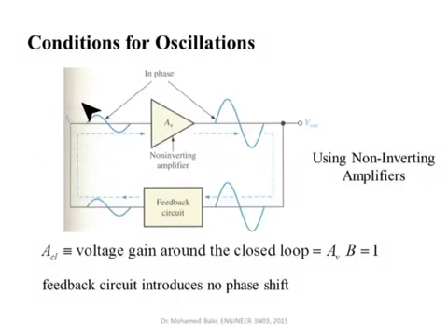So if this was 1 volt in amplitude, this is 10 volts. You take this 10 volts amplitude and then you attenuate it, and you get the same signal. It's still in phase with this signal here, but attenuated by multiplying it by 0.1. Then you recreate exactly the same input signal. So we say if the gain here is equal to 10 and the attenuation is 0.1, then the product of 10 and 0.1 is equal to 1.